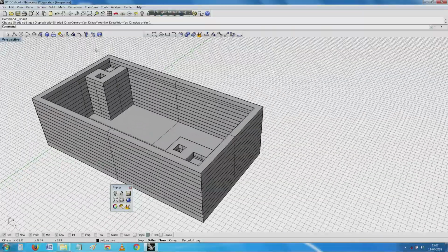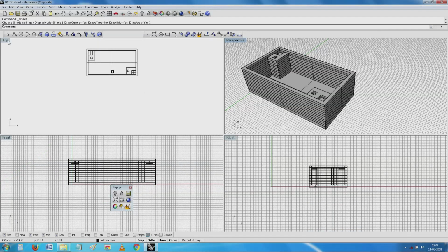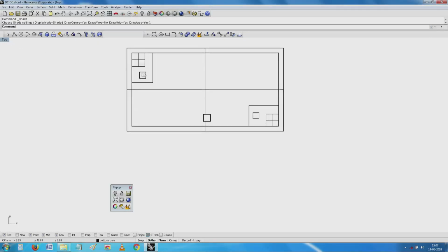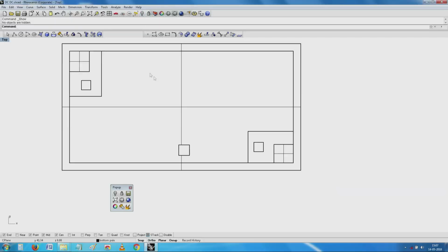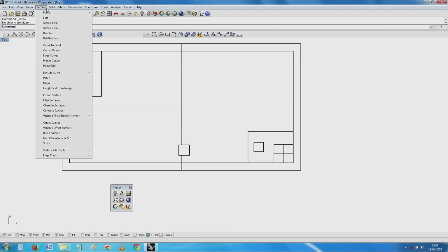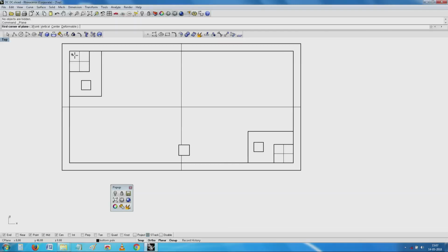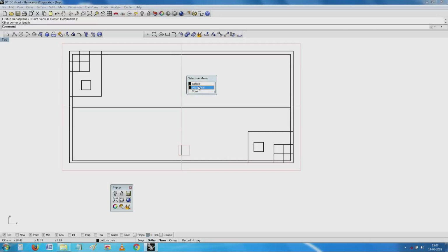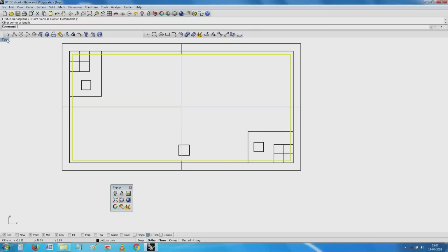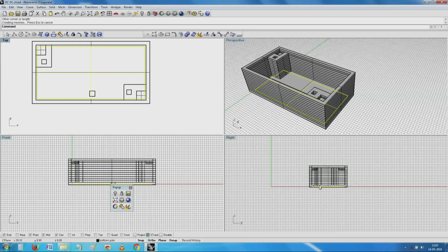To simulate a small printed circuit board inside, again go to the original drawing here, and then I try to unhide all those things in case I have them, and then I will try to make a simple surface, a plane, move the plane up,